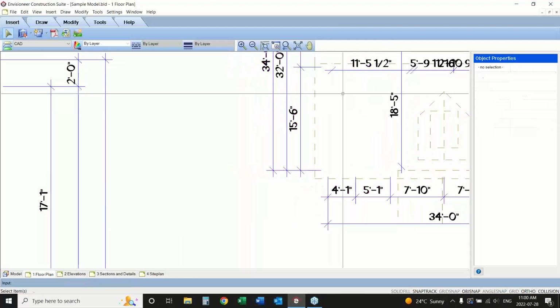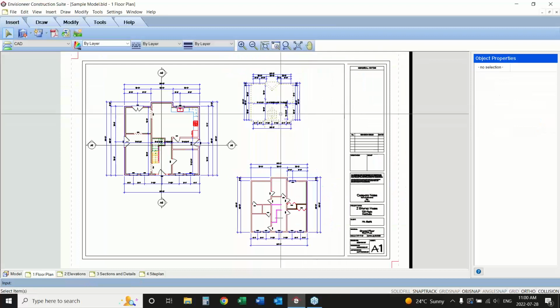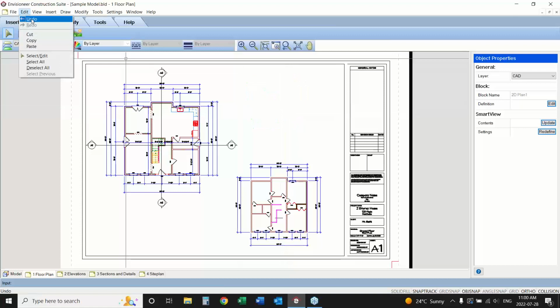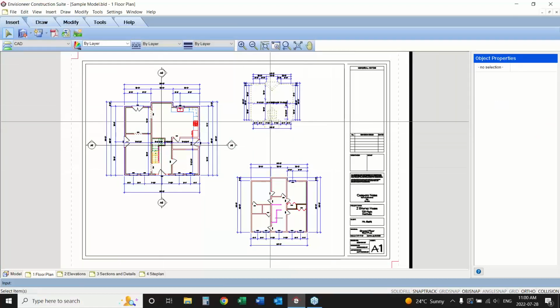Okay, there's no difference in the size of the text, but it does scale the actual model itself. Okay, so that does update and change. But whoops, edit, undo there. The model size itself is always going to update depending on the scale, but the size of the text will not. Okay, so it's a nice, consistent way to read your drawings and blueprints on the one sheet. Okay, so 3 different views, 3 different scales, and we've got that one sheet done.